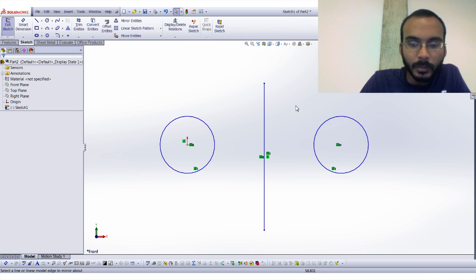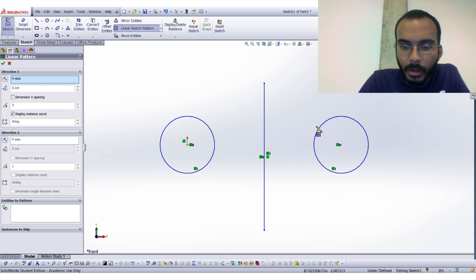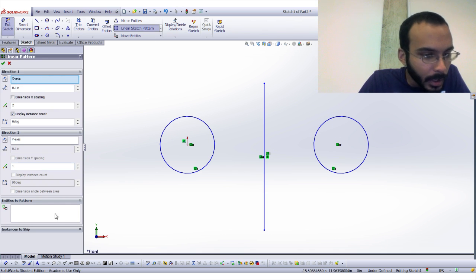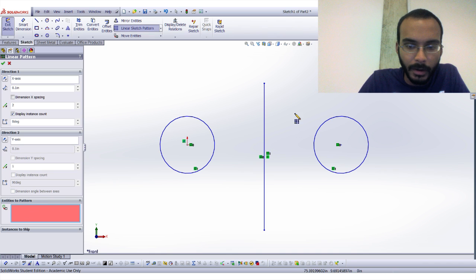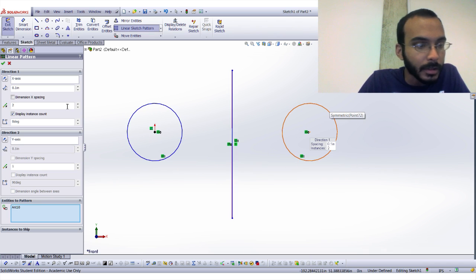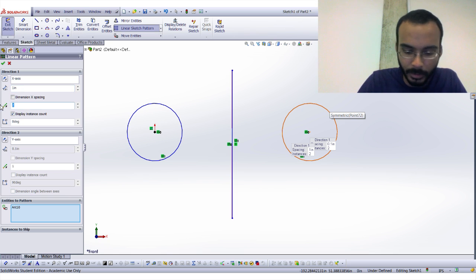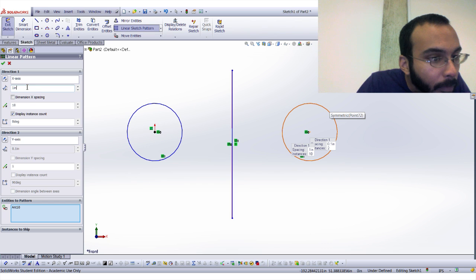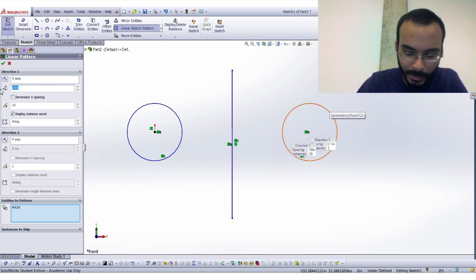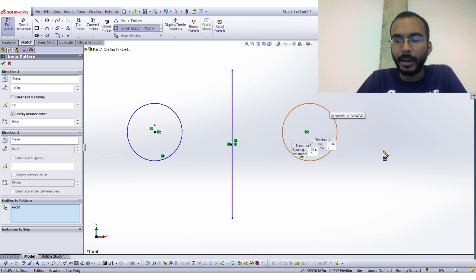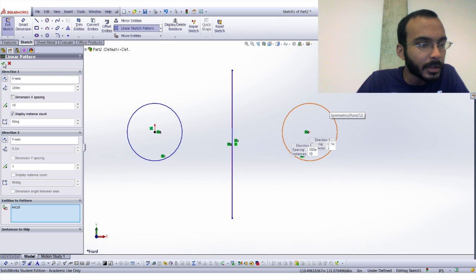Okay. On that same note, you can also use the linear sketch pattern tool to go about sketching. So you want to select entities to pattern down here, and it'll sketch whole patterns and things for you. So like all of those nice pretty sheet metal robots that have all the crazy numbers of holes in them, that's all from being able to do things like this. What? Wow, I'm drawing in way too large of scale. Okay, 10 inches on circle. Nope. All right, 100 inches on circle. There we go. Okay, so you can see that you get nice long chains of holes like you would.